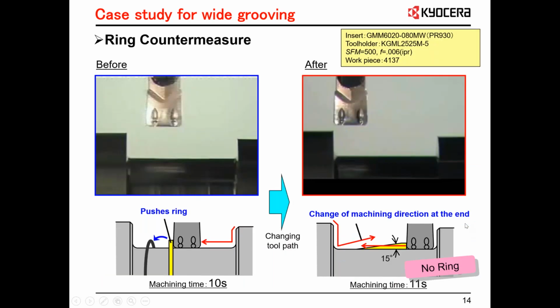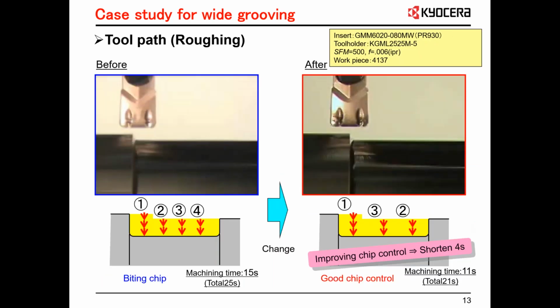So to go back, you don't want to ever do a 1, 2, 3, 4. That's only going to wear this side of the insert as you go across. By alternating this way, 1, 2, and then 3, your insert is completely engaged in every single plunge, even in the center plunge. We leave a little bit more on the sides to finish up, but that's not an issue.